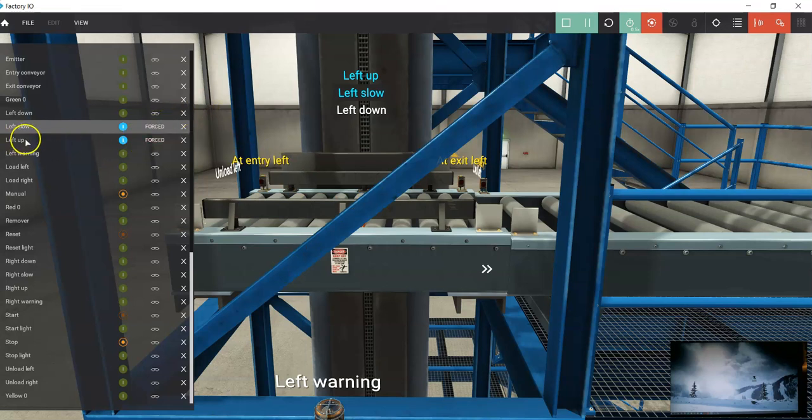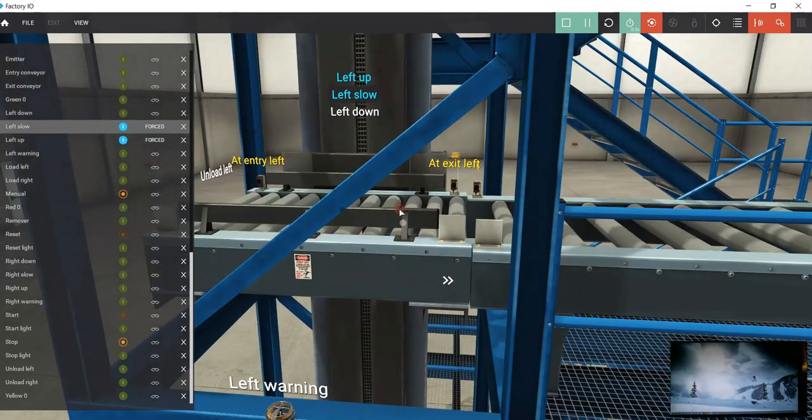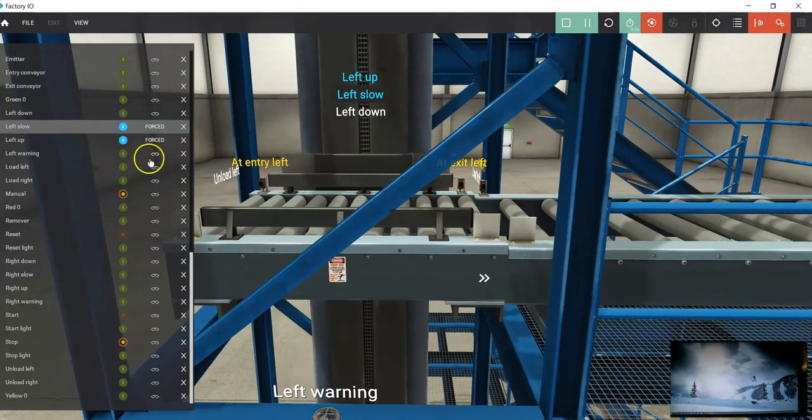And you have to use the lift up and lift slow in combination to get it to the right level, because if you don't use the lift slow, you will always overshoot. I mean, even when I was using it just now and I was trying to eyeball it, I didn't get it at the right position. So the odd thing about this is when you're going up, you can use lift up to get you 90% of the way, but then you have to turn on the lift slow to get you to the right position. And that's kind of all I'm saying here.